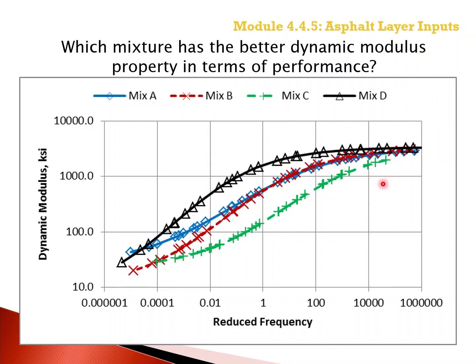For bottom-up fatigue cracks, mix D would have the smallest area of predicted bottom-up fatigue cracks. In other words, it's the stiffest mixture.